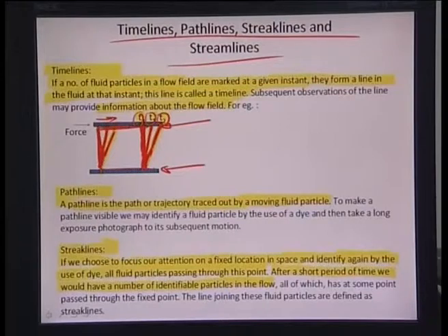All of these particles of course float through that same fixed point. Now, the lines that would join these fluid particles once they are out of that small point and somewhere along the fluid after that point, the lines which join all those particles which came from this one spatial location is known as a streak line.